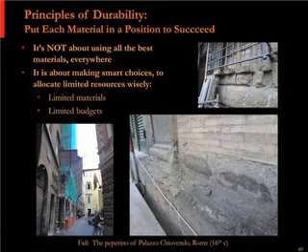And at the top right, you see some of that stone deteriorating, and that's actually what you can kind of glimpse in the photo at the lower right on the left-hand wall. That's a close-up of one of those areas. And that stone's really going quickly now because those roofs are no longer protected. So if you think about originally, all these houses had roofs intact, and basically they've left the roofs where they survived, and they haven't built up these shell walls to cover them. So the ones that are uncovered, like in the photo at the lower right, the tufo is really deteriorating. The ones with their nice overhanging 12-foot roof, as you can imagine, are doing very well.